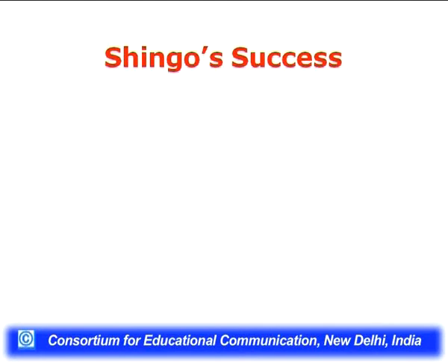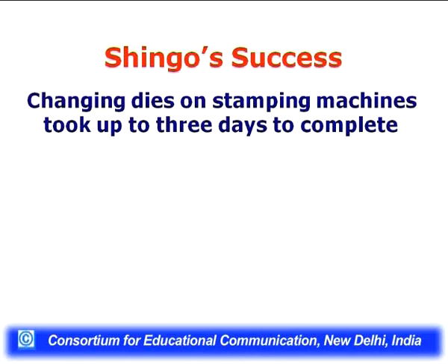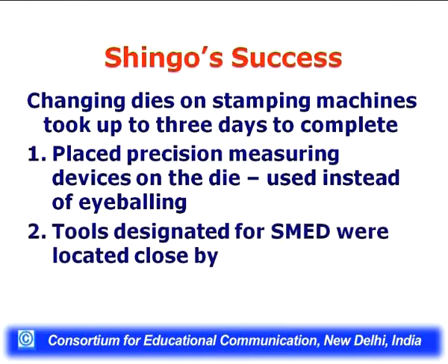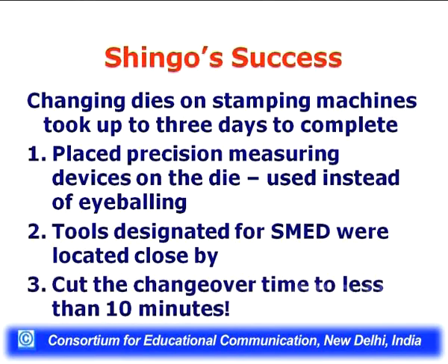Shingo's success. Changing dies on stamping machines took up to 3 days to complete. Precision measuring devices were placed on the die instead of eyeballing. And tools designated for SMED were located close by, and no time was lost in locating the tools required during the changeovers. This cut the changeover time to less than 10 minutes.